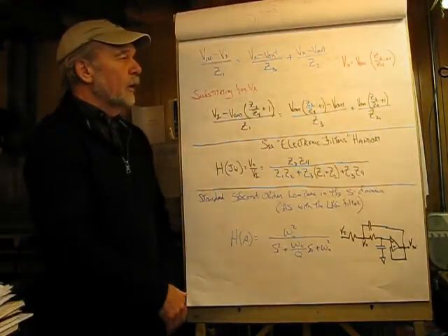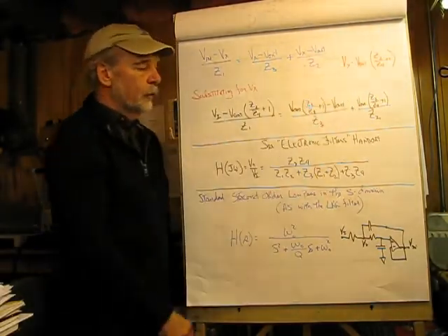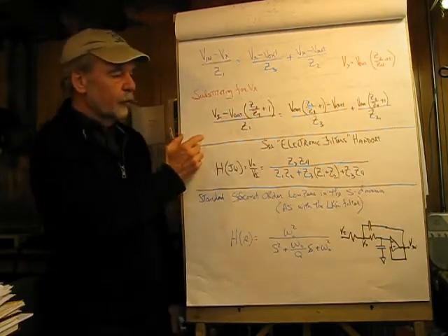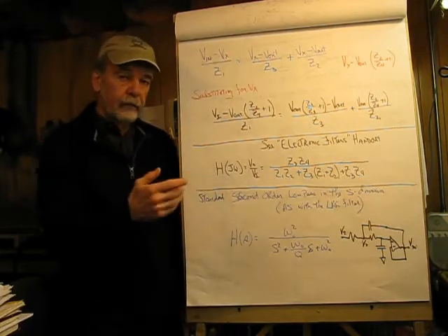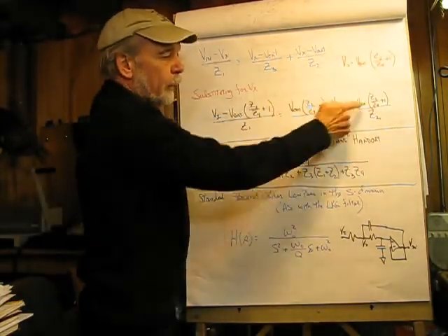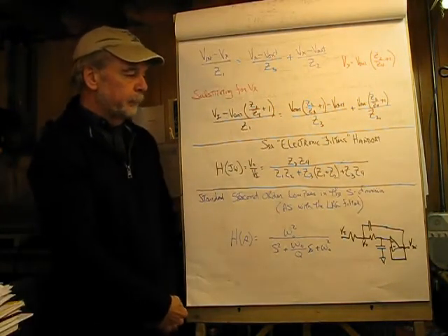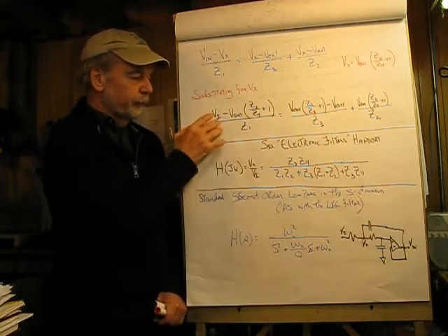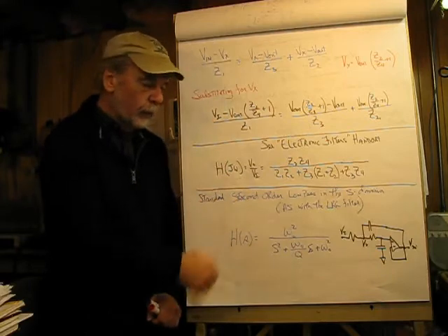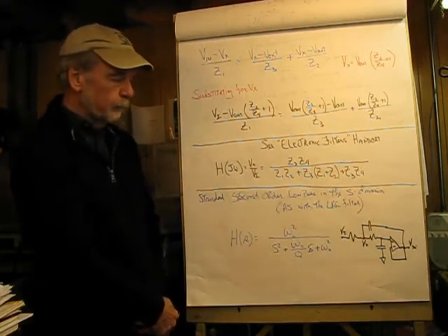And repeating the equations here, this is what we started with, and this was our Vx substitution, and this is going to lead us to the equation with the substitution. And you can see wherever we have a Vx in the equation, we've substituted in this value here, and now we basically have two unknowns. And what we want to do is get this Vout over Vin in terms of Z1 through Z4, and then we can worry about populating those with actual physical values.